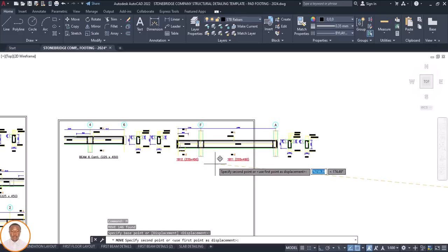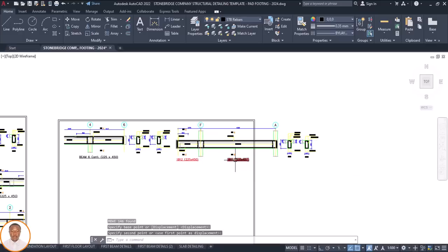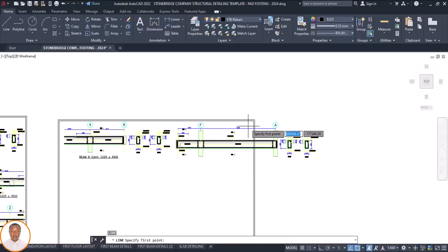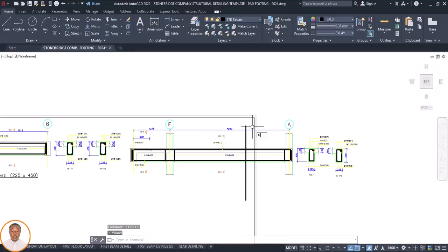So that is that. Okay, let me put it here also. Let me remove this. Is that okay? Then L, enter. Let me pick it here. Okay, then click on this, then explode it, because if you don't explode, you will not be able to trim it. Is that okay? TR, enter. So I come to this place, click on this. Be fast. Come up.